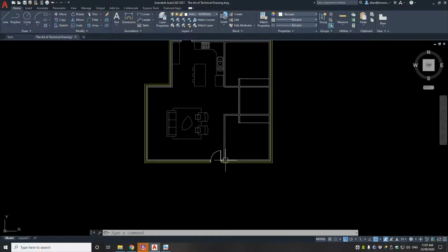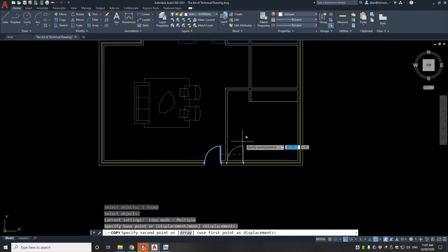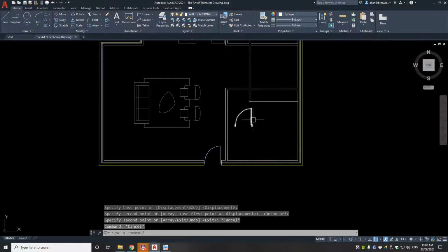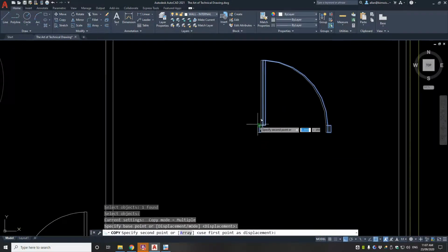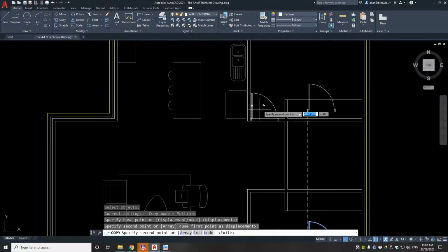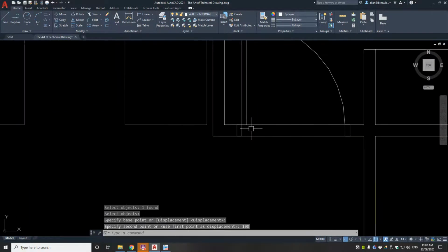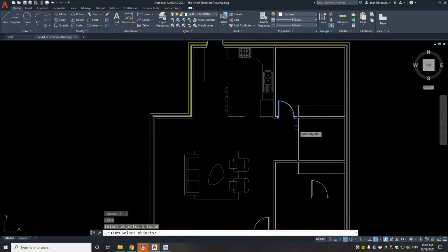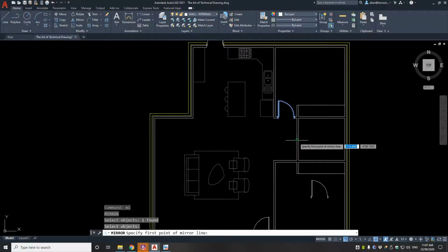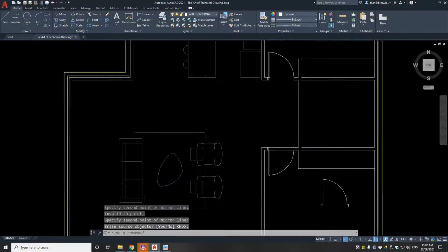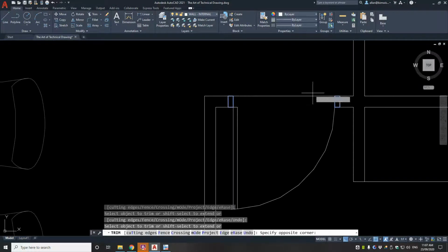And I haven't got the door in there, so let's copy those doors up. Copy the door up. It has to swing. Okay, so let's mirror that door around that axis, and I'll copy that one up to here. Move that over 100. Normally it's 90 jam, but 100 will be okay. And let's trim it to that. There's the door to that. Now I'm going to mirror this one. Mirror from that one. Click, right click, midpoint of the bathroom down to there, and that's right for that one too now. So that's great.